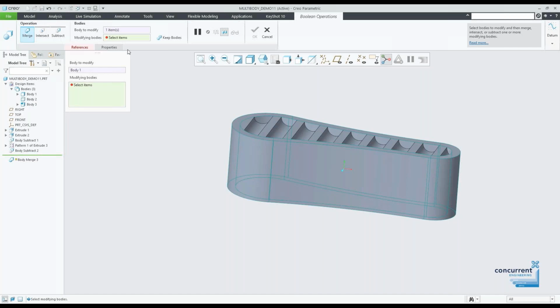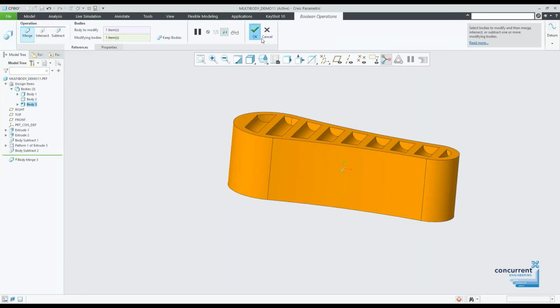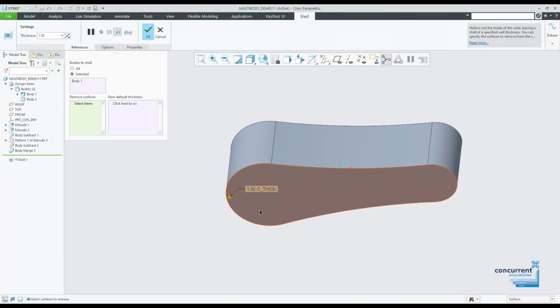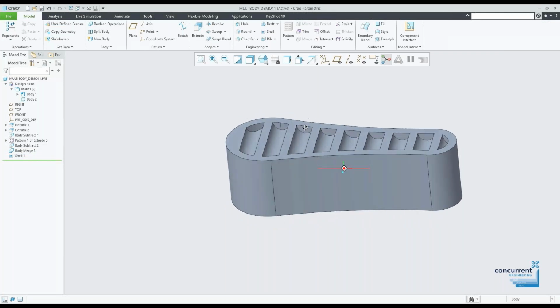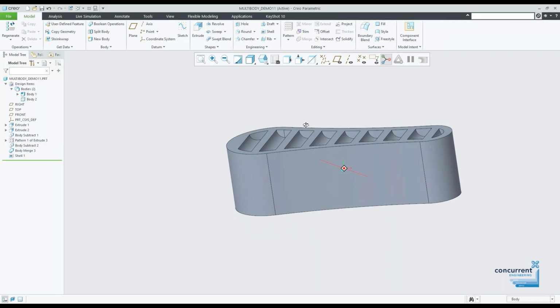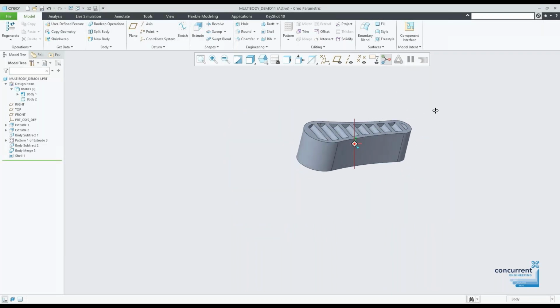So if I then select all 3 and put them as a merged entity, I'm going to say, OK, this one, modify this one, and it creates one body. So then further manipulation, for example shells and things like that, would work as required. So I say that surface there, say set it at 2 mm.